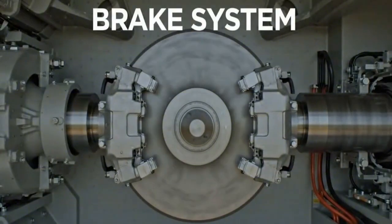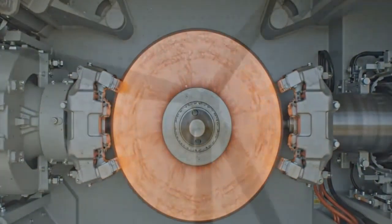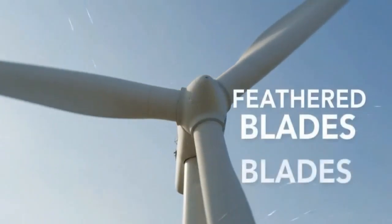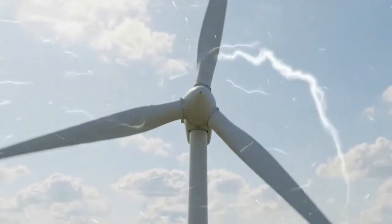Sensors continuously check wind speed, rotor speed, vibration, temperature, and generator load. When overload risk is detected, the controller sends commands to the pitch system and the drivetrain brake. The brake system sits in the drivetrain and helps slow the shaft when the turbine must stop or protect itself.